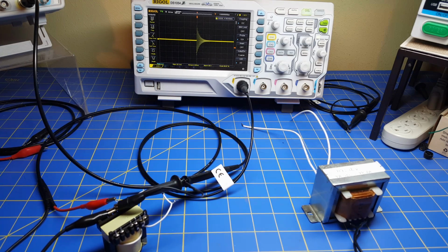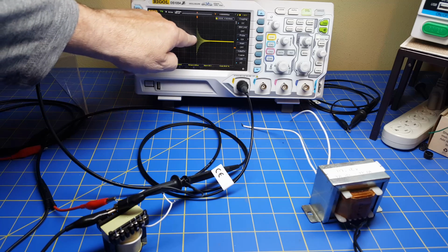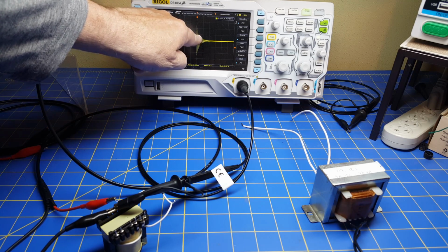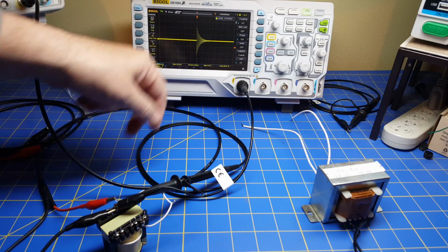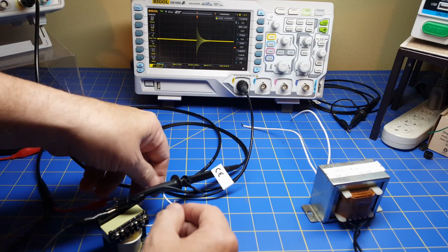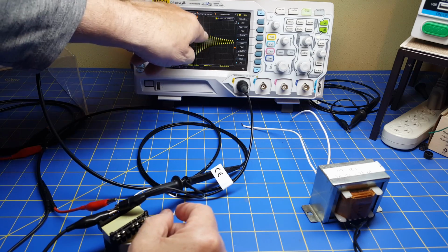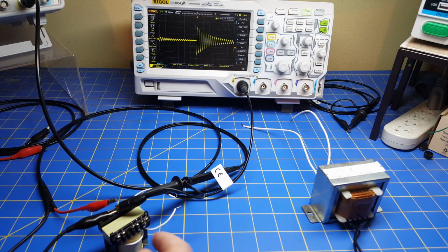And the testing circuit that we're going to be talking about is called a ring tester. And you can imagine what it does is it looks at the number of rings over a period of time. With the short circuit, there's going to be fewer rings, as you see here, than without the short circuit, where there's going to be more rings over a certain period of time. So we're going to look at what's going on here, what's the basic concept, and at the end of the day, is it going to be something that's useful to you?